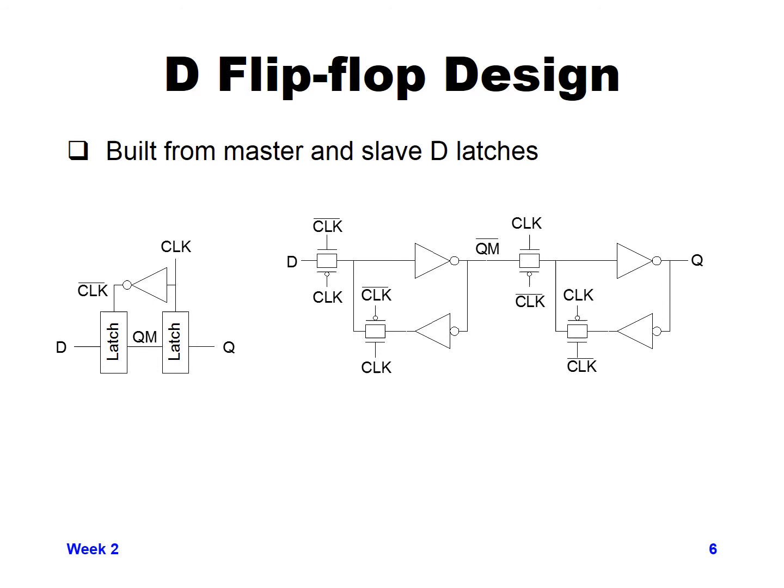And this causes us to get a nice, good, strong value of Q out, rather than going through two pass gates and having a degraded value of Q going out. So this is one of the lowest numbers of transistors required for a D flip-flop, and so it's typically the most common that you'll see.